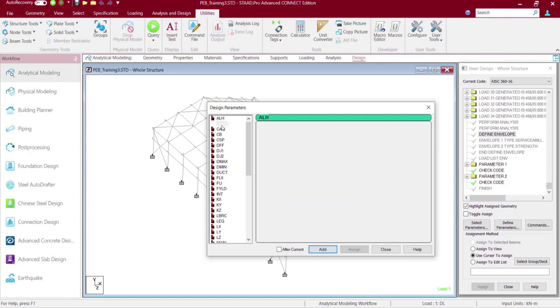So these can't be treated as pure hot roll sections because we are not bringing out the entire section with that cross-sectional shape directly out of the blast furnace and giving it the shape just in the molten state. So it's not cold form, but it's a built-up section.